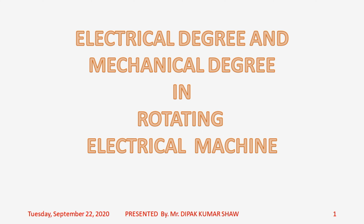Although you are already accustomed to this particular relationship, which says that theta electrical equals P by 2 into theta mechanical, I just wanted to give an even more detailed description of it. If we make a formal derivation of this relationship between electrical and mechanical degree, it will help us derive the expression of induced EMF in a coil.